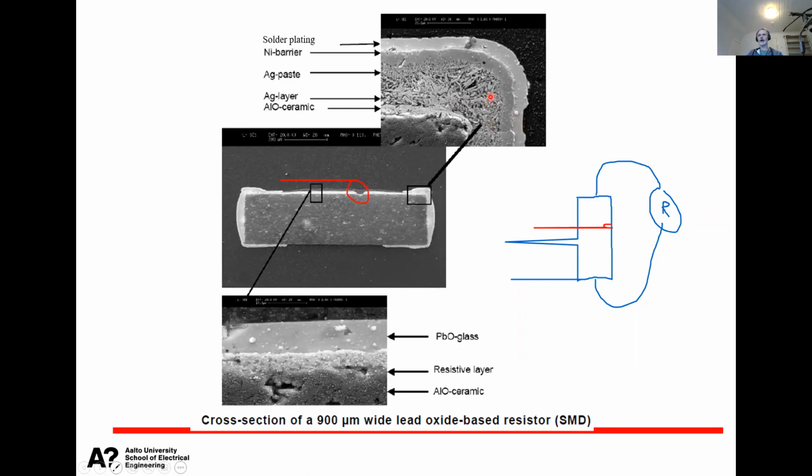First of all, silver makes the solder harder, so less ductile, and silver also has a tendency of migration. It's also very reactive, especially if there are sulfur containing impurities in the ambient. And this is in fact what we are looking at next.